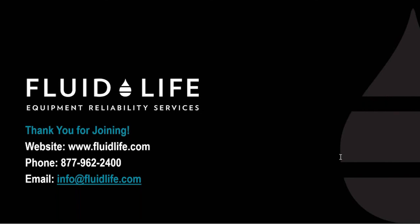But what you can see is some ash and some dust that can be exposed to it with potassium, because you can have hatches open for heat, or say your fans aren't working, depending on platform for the turbine. So there is a potential to see potassium ingression, but it's probably a little bit less common than, say, your sodium, for example, which can come from water ingression, because if there are ambient temperature changes, these are up tower in the air, you're going to see some of that stuff.